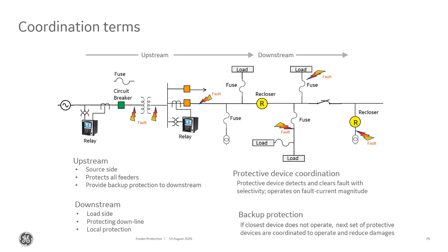That's a dangerous condition for that person in the manhole. The copper melts, the insulation melts, it can cause dangerous toxic fumes apart from the arc flash issues. So it's a dangerous condition. What we ended up doing was we set the recloser on a high speed curve. And we set the relay to coordinate with that high speed curve so that the relay will trip faster, so it does not have to coordinate with the slow speed curve of the recloser.